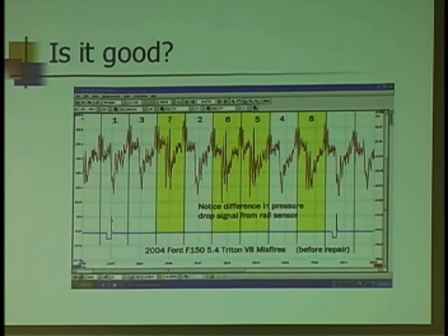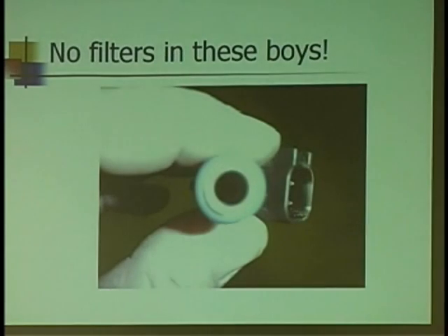It'd be like holding the injector up out of the rail and watching it splash out all nasty looking. But that's a lot of work. You know, I'd pull the rail and get out my paper cups, and so I pull the injectors off. I don't know if you can really see it in this picture, but there's no filter in these OEM injectors. That's the way they come. So if it got past the fuel filter, it got to the injectors. And we knocked them out, and you can see the crap.